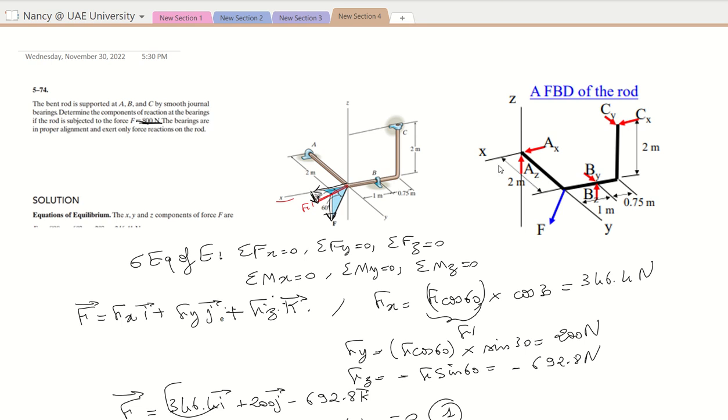To understand it better, just compare By with Cy. If I move By upward, it will have moment. But since By is exactly on the plane where the x-axis is, the perpendicular distance between By and the x-axis is 0.